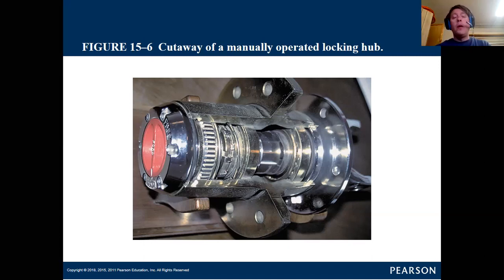In the beginning, it was done with mechanical hubs. So here we have an image of a Ford. Fords were common with this. Jeeps had these. There's all kinds of different manufacturers that use it. Chevy used them. You saw them on, like, a Dana axle or whatever, because all manufacturers back in the day used other axle companies' axles. They just contracted with them, and so whatever. So this is a mechanically locking hub, is what's in front of us here.